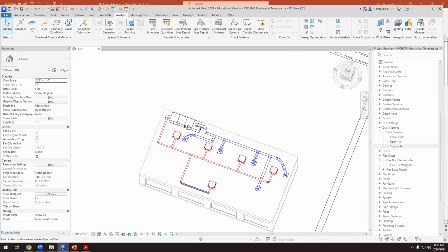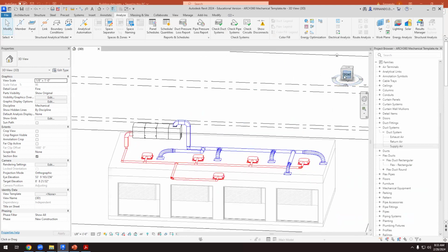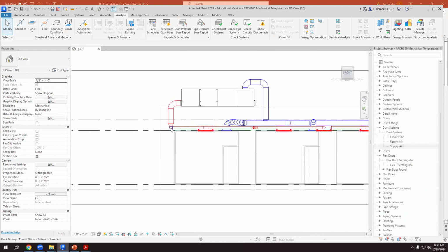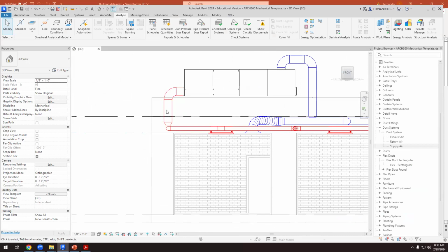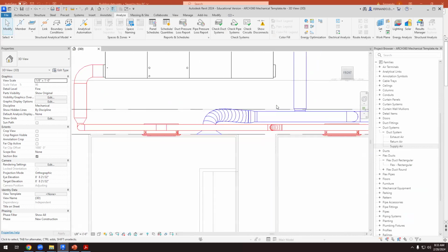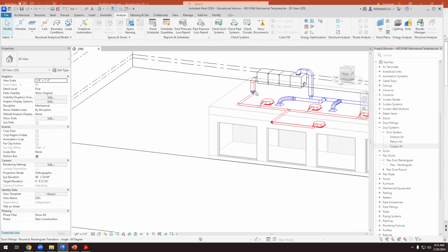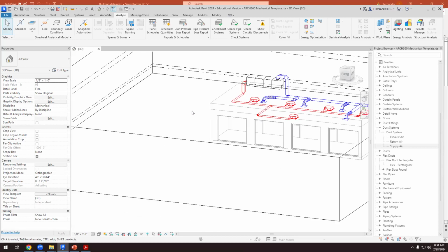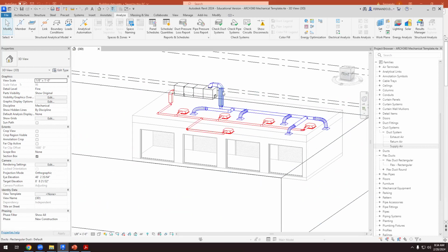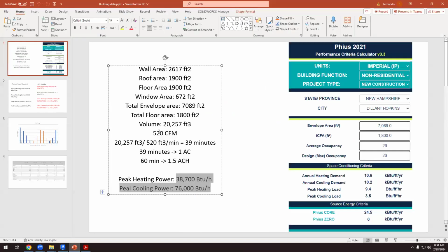Why can't we do this with Revit? Because look at this, we are going through the roof with a pipe, and Revit doesn't like it because that means that we have perforated the roof. So that will affect the space that we have created there. So that's why we use a different file to do the mechanical system with Revit. We don't simulate it. Anyway, we did this before.